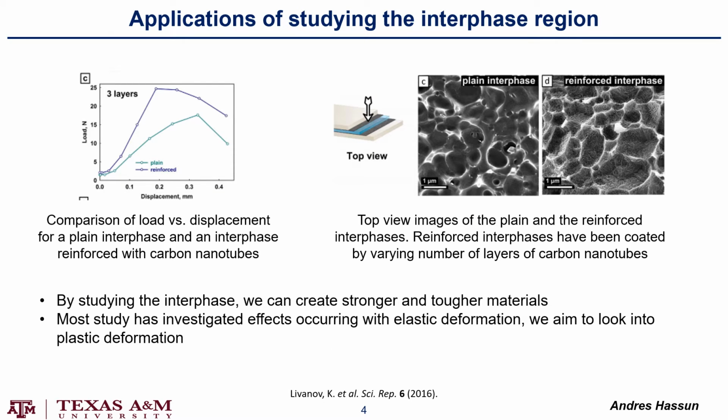So some of the applications of studying the interphase region is that we can create stronger and tougher materials. Large deformation is important to study as the material is stronger if only the particle carries the load, but will fail if the interphase debonds between the particle and the matrix. The interphase region is critical in controlling a lot of the properties when undergoing plastic deformation. So we aim to look into plastic deformation, while previous studies have mostly focused on elastic deformation.